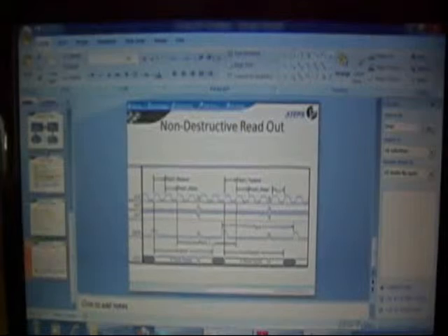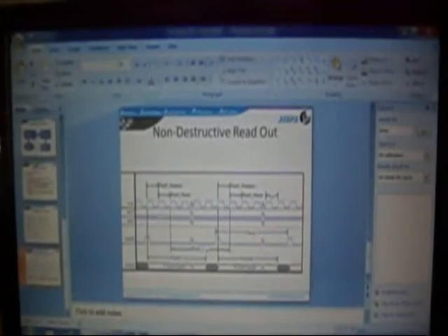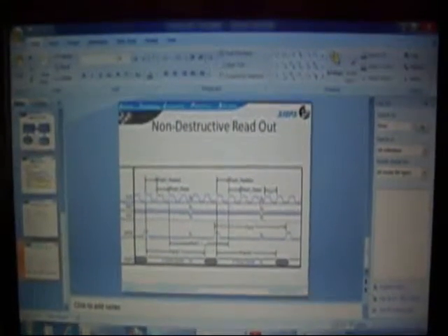Most of the online applications are high-speed systems for a flow of material which has to be subjected to an imaging unit, and the defects, abnormalities, non-linearities or a product mix need to be identified, and some defect elimination mechanism is in place, for example a pneumatic suction.